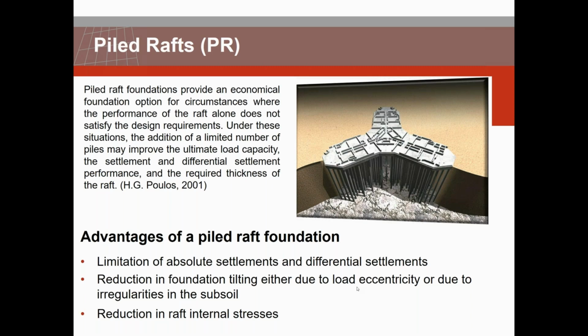In terms of advantages of the pile raft foundation, one is the limitation of absolute settlement and differential settlement. Another is the reduction in foundation tilting, either due to load eccentricity or due to irregularities in the subsoils, and the reduction in raft internal stresses.